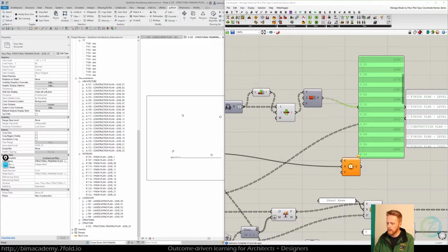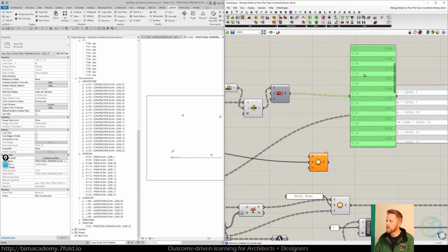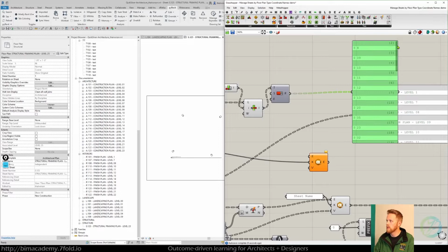All right. Final step I want to do is a format, because at the top here I've got this 8, and maybe there's other single-digit codes that really need to be a 2-digit code with a leading 0. So if you want to do that, I'm just going to do the format component. And the format culture we're going to put in a second. We're going to feed this information into 0. And then the culture, just do a panel, so quotes, and then let me zoom in here.